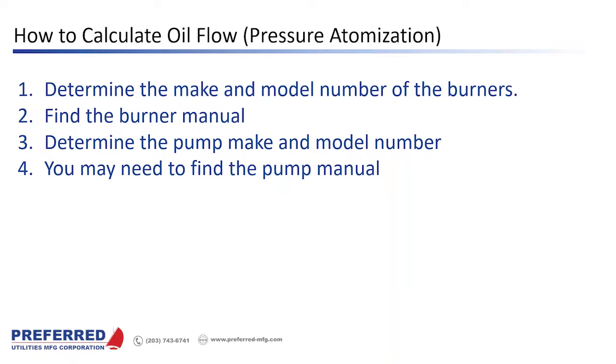Once you get that, find the burner manual. All the European burner manufacturers have their manuals online in English units. It usually doesn't take me very long to find the burner manual. Dig through the burner manual. Some are better than others. Most will tell you what the flow of that pump is. Some will not tell you the pressure limitations on that pump.